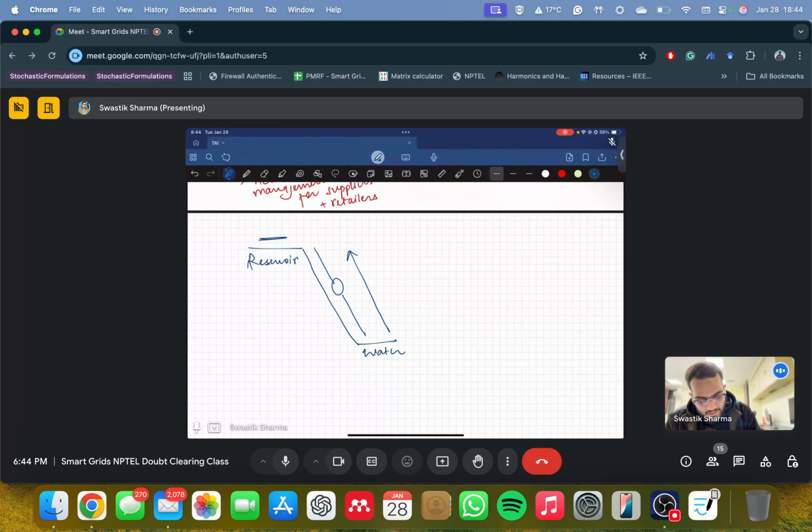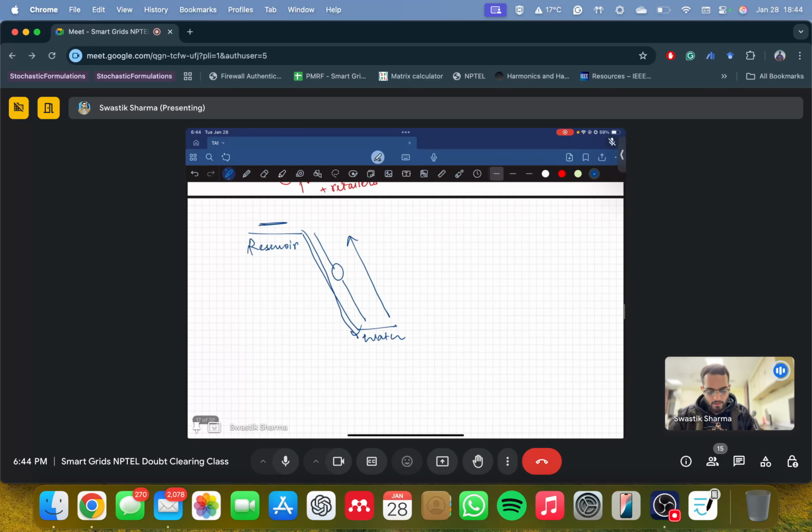You pump it, and then when energy generation is low, you supply this water back through a turbine. And when it hits the turbine, it works on the same principle as a hydroelectric power station. It rotates the turbine, it generates electricity, right? And you do this just as if you are doing it with a battery. So this is something that people have come up with, pumped hydro storage plants. These are not something that you use in your homes, but people are doing research on that as well. But I don't want to go into that. But this is something that people are doing.